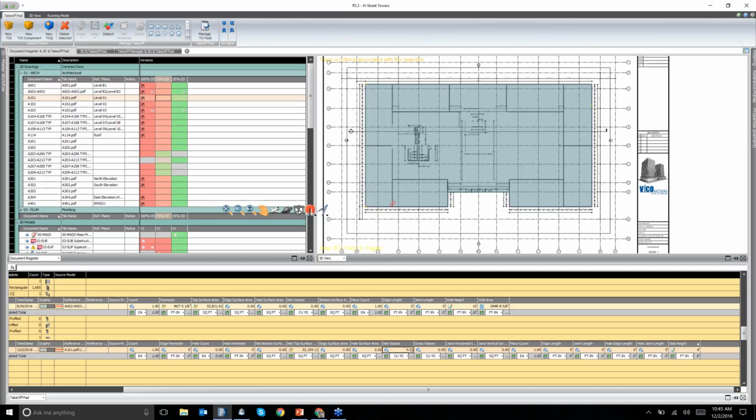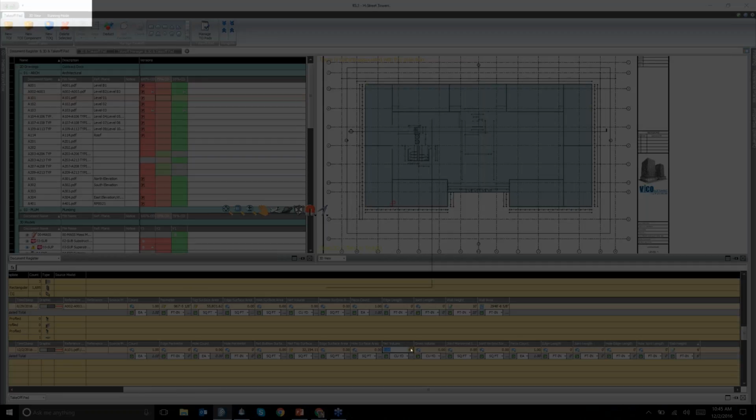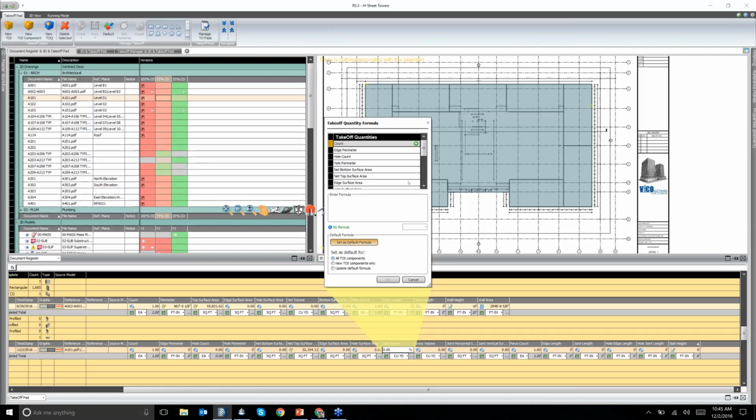So what I'm going to do here, if I click on that quantity area here, I get a little button here, FX, which means formula. What's popped up is a takeoff quantitative formula calculator. So what I can do is actually leverage quantities that I've taken off. So what I want to get is the net top surface area, hit the plus sign, brings that in there. I can use operators that I use in Excel, so I'm going to use the multiplication. And I'm going to multiply that by my slab height. Now, what I can do is click OK and watch this quantity here, net volume.